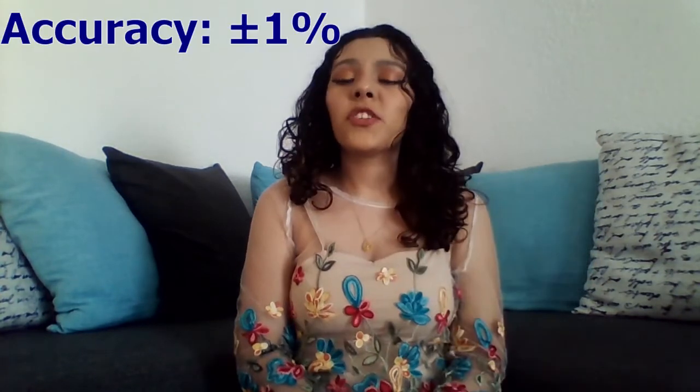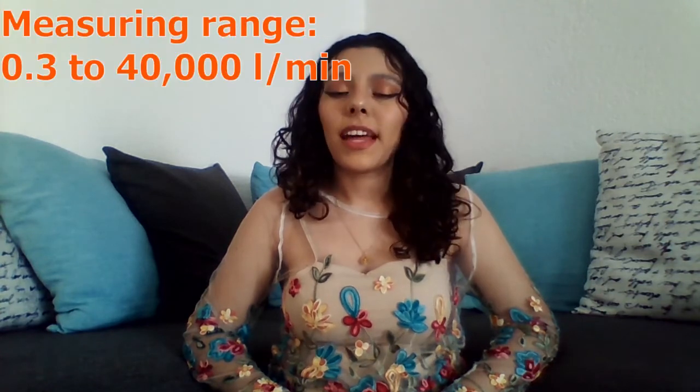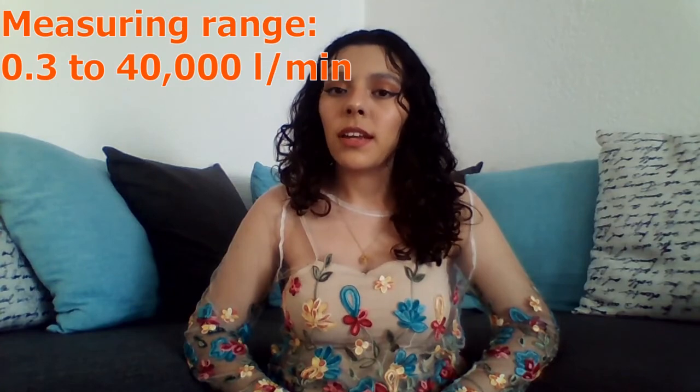If you want to know more about all these transmitters, I will leave you my video in the eye for you to check. The measurement accuracy of this instrument is ±1%. In addition, it allows the passage of fluids with small amounts of suspended solids and can measure flow rates ranging from 0.3 to 40,000 liters per minute.